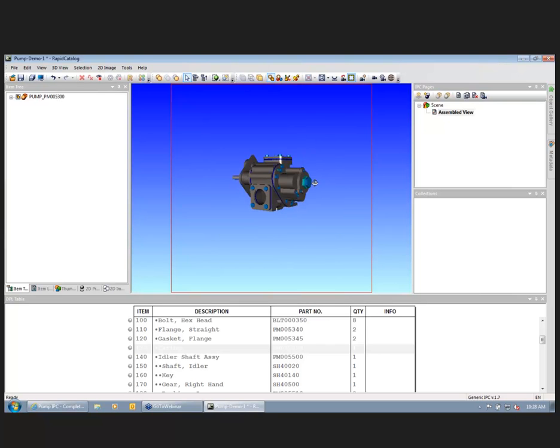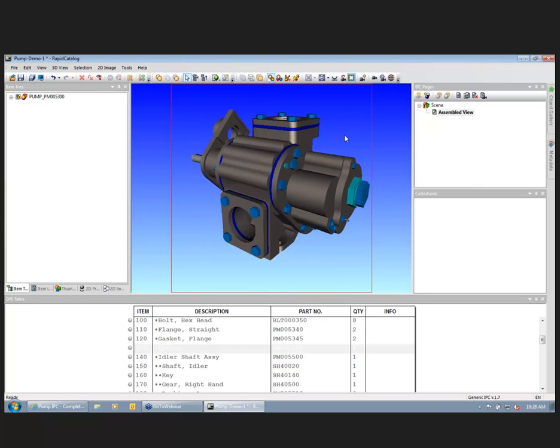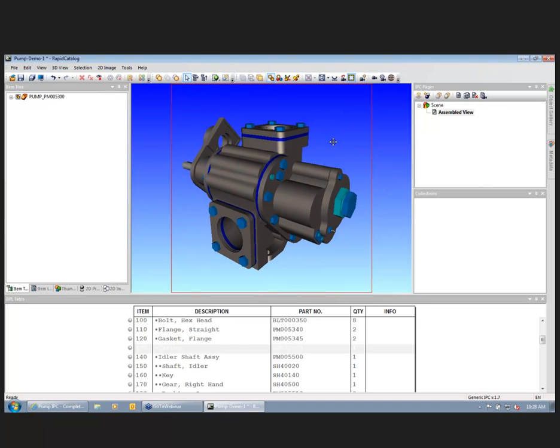And the next thing I want to do is set the viewpoint for that page. This is going to be the position of the camera when I activate that page. So notice that the page that I'm working on right now is shown in bold. That's the activated page that I'm applying commands to. Now that I have the view the way I want it, I can come up in here and set Page Viewpoint. That's where my camera is going to start.